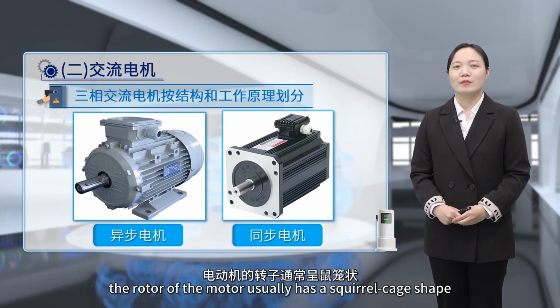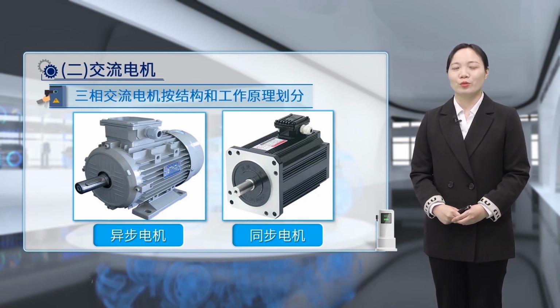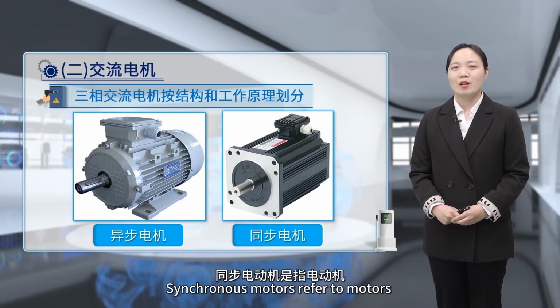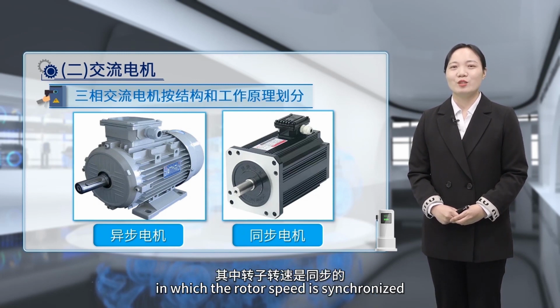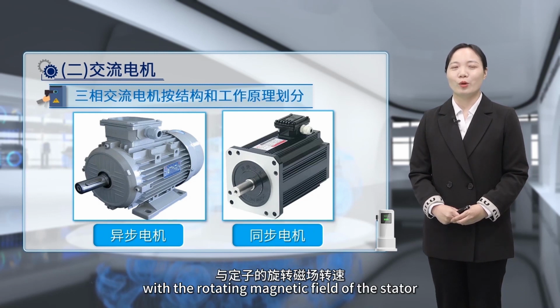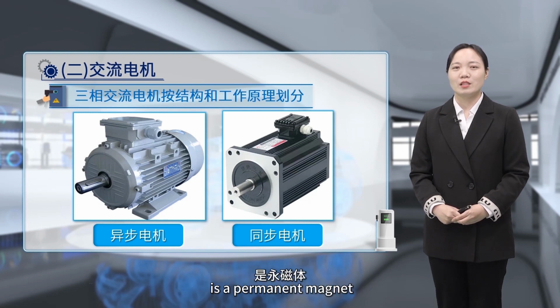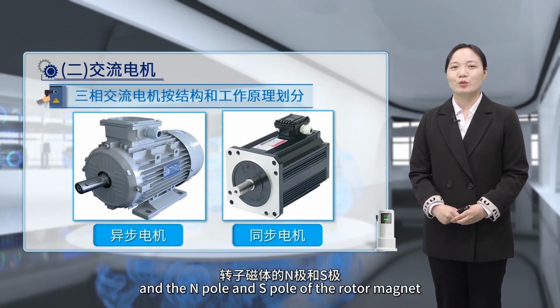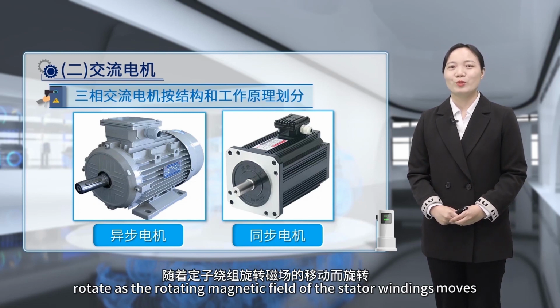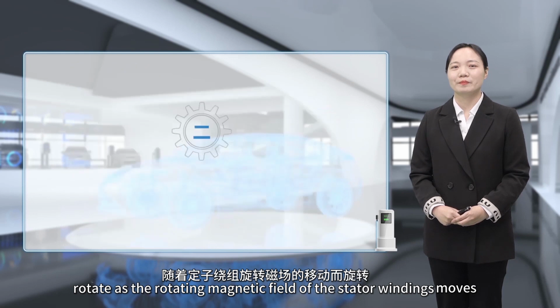Therefore, the rotor of the motor usually has a squirrel cage shape. Synchronous motors refer to motors in which the rotor speed is synchronized with the rotating magnetic field of the stator. The rotor of the synchronous motor is a permanent magnet, and the N pole and S pole of the rotor magnet rotate as the rotating magnetic field of the stator windings moves.